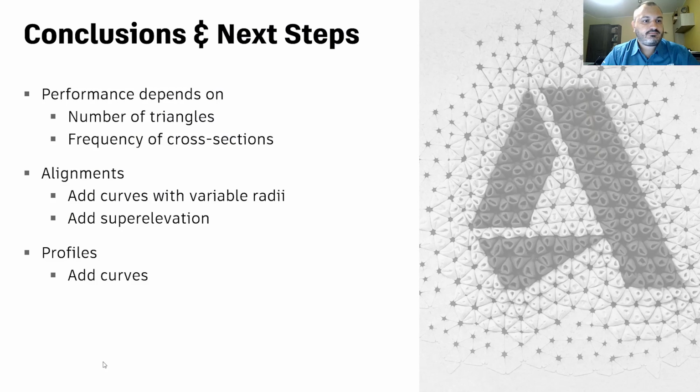Conclusions and next steps. The performance is really critical when it comes to generative design. Every second counts. So what I ended up doing for other customers, for example, is develop my own geometry library to represent the mesh, to represent vertical profiles and so on, so that I could keep an eye on the number of elements that were processed by Dynamo. The number of triangles plays a critical role here because they participate in the intersection of multiple elements, either the profile or the cross sections.